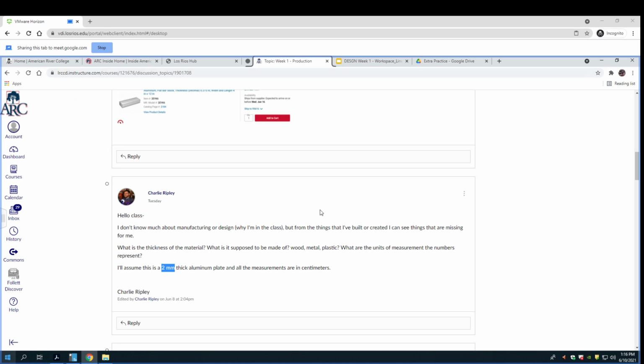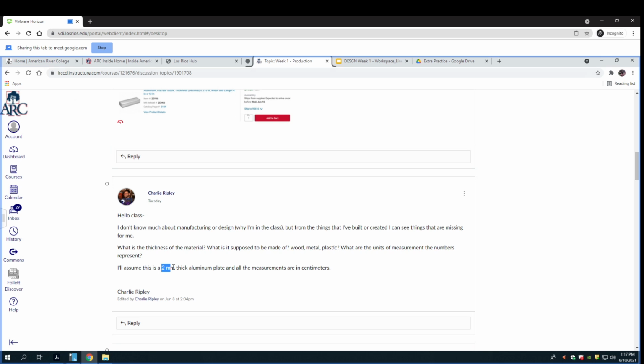because we just sent the drawings, AutoCAD, and they threw them into the machines, and their machines read 1 as a millimeter, and our AutoCAD read 1 as an inch. So we had 1/25th scale valves. And so machine tools, not just people, but machine tools have to know what your units are. And you'll see that on 3D printers a lot too.